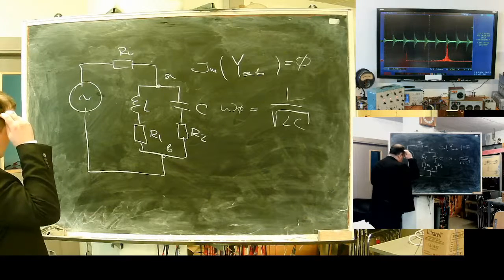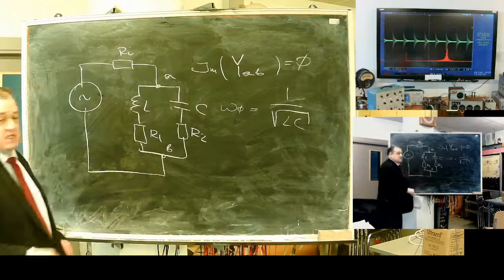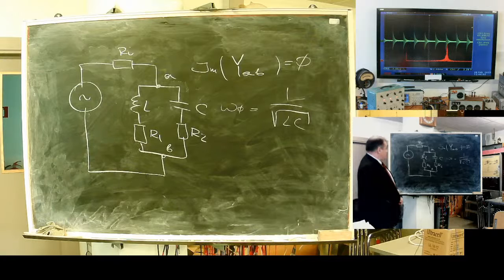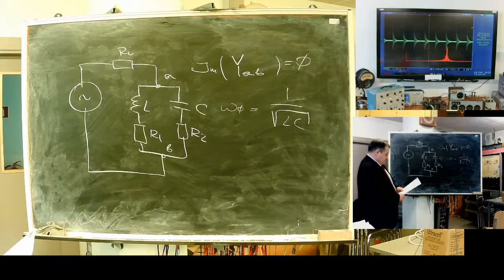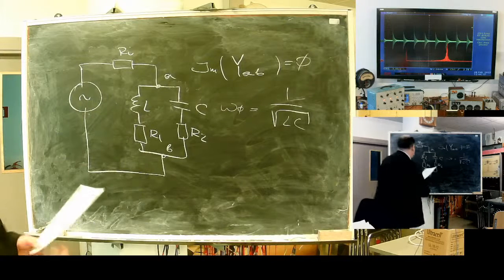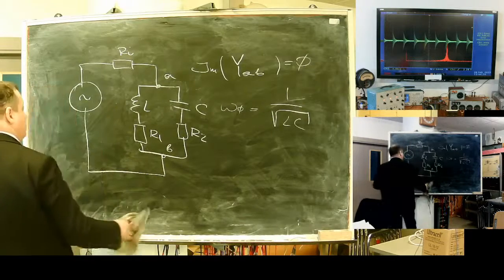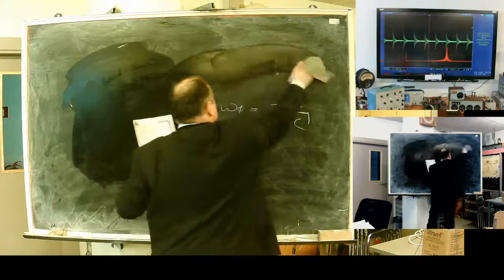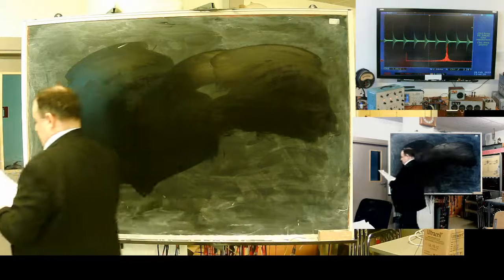At the point of resonance, the internal contour resistance is very low and the current achieves quite significant values. That's why such parallel resonance is called resonance of currents.